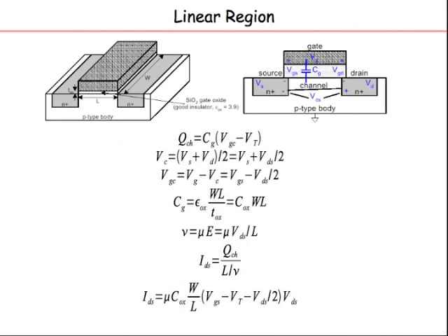Why is that important? Because of power. And area. You would like to use the smallest area possible. So if the technology allows you to define the minimum channel length and width, you would want to use that, because then you can keep the area small, and area translates to cost. It turns out cost translates to profits, money, etc. So area you want to keep small. We'll see as we go along what the implication is. When you keep the width small, you don't have that much current.